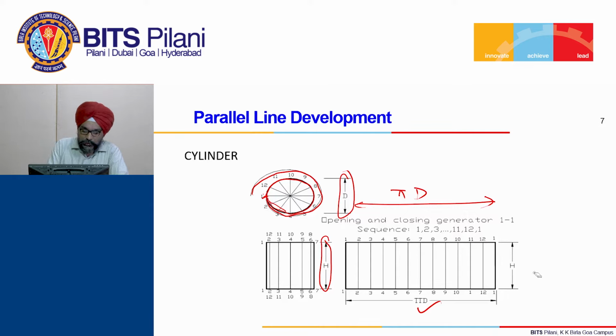This is useful when, suppose, you have a certain curvature and you want to manufacture a solid with this curvature, which will have a curve like this in the front view. In that case, we will need to transfer these points onto the development, and we may be able to see what kind of profile results, because the different points will be joined together.